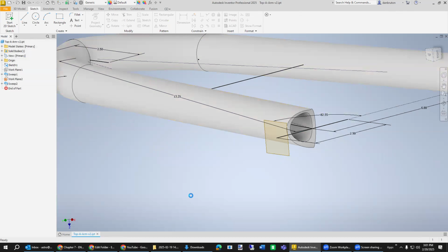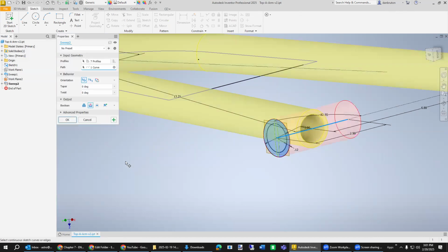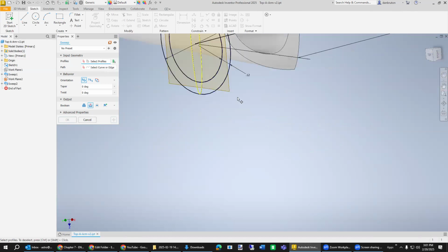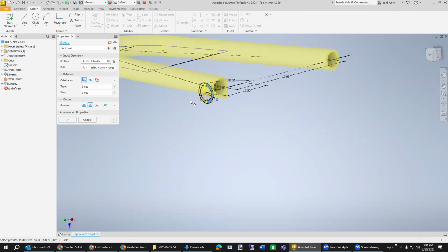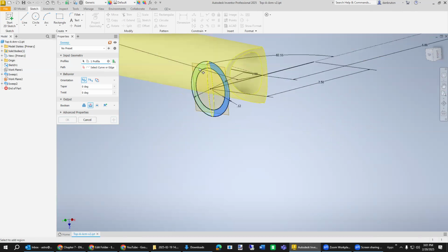So that looks good. Now, what I should have done though is done another step where I do the extrude. So I can't come back over here and then edit this feature and say I want something else also. So after I finish this sweep number 2, I can say, you know what, it's time for sweep number 3. And so for this one, that's automatically selected there, but I want to select the donut now. Right there, the ring, and it looks like it got bisected. So I'm also going to select that side.